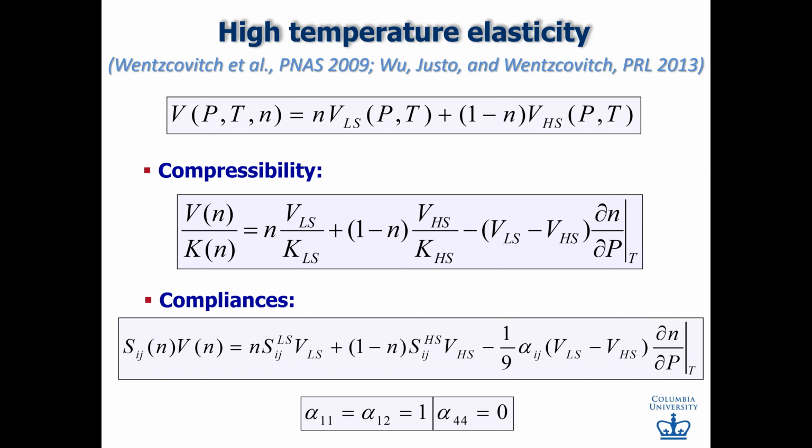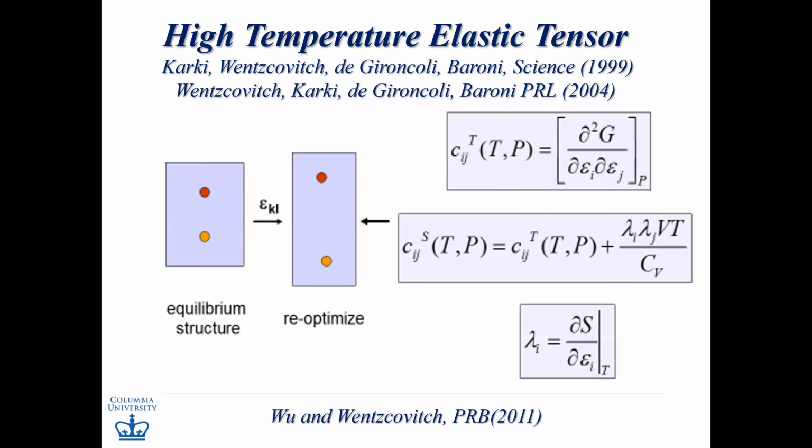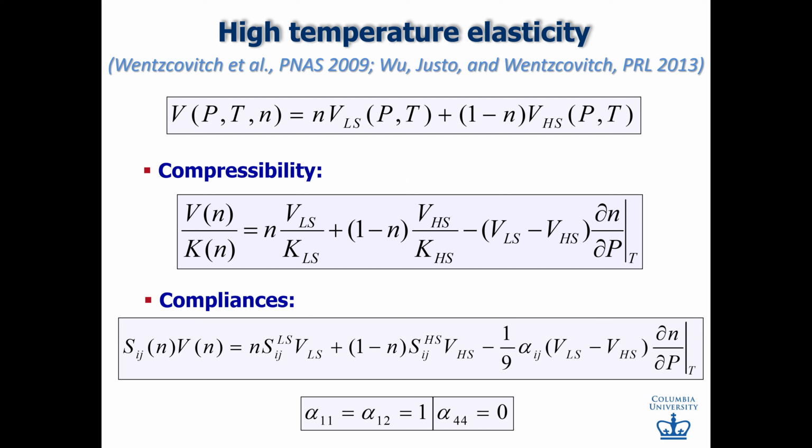In this case, we showed that the shear elastic compliance component does not have an anomaly. In other words, the shear elastic coefficient does not have an anomaly. It's the longitudinal elastic coefficients that have anomalies. Also, with this formalism, you needed to calculate the compliance tensor of the end members only, not of the solid solution.